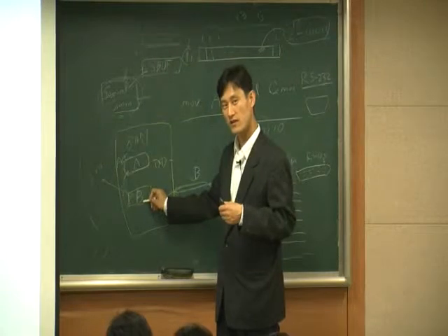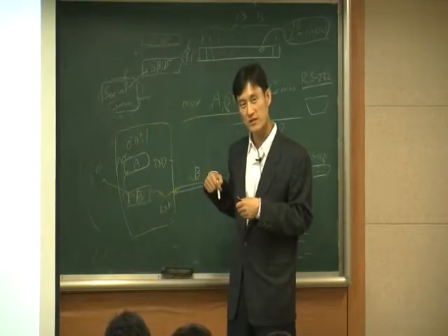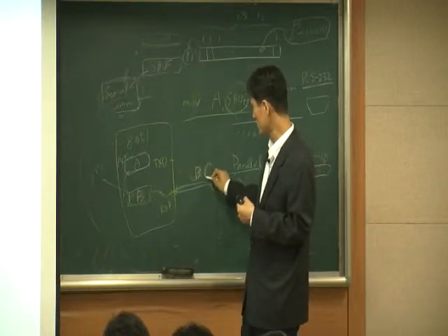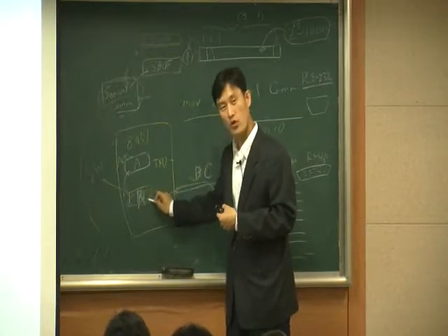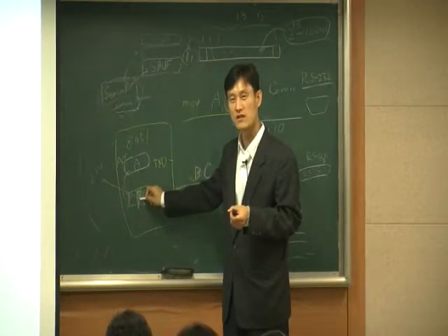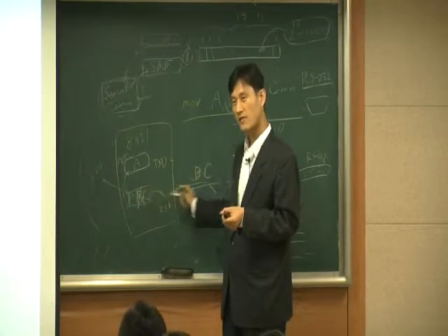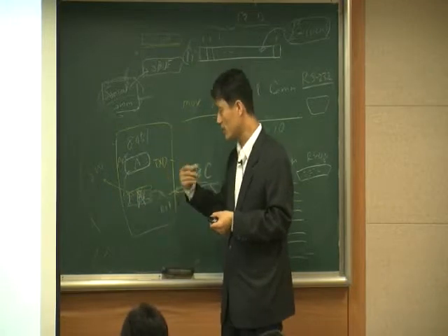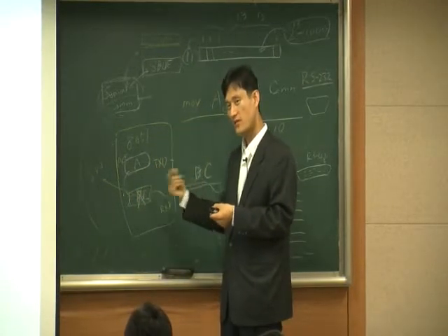Then what you need to do again? You want to read the value out. If you don't read it, then a little bit later it will transmit C. You're going to overwrite the C, so you'll lose it. Right? Every time you have data, it's overwritten. So you need to read it every time.